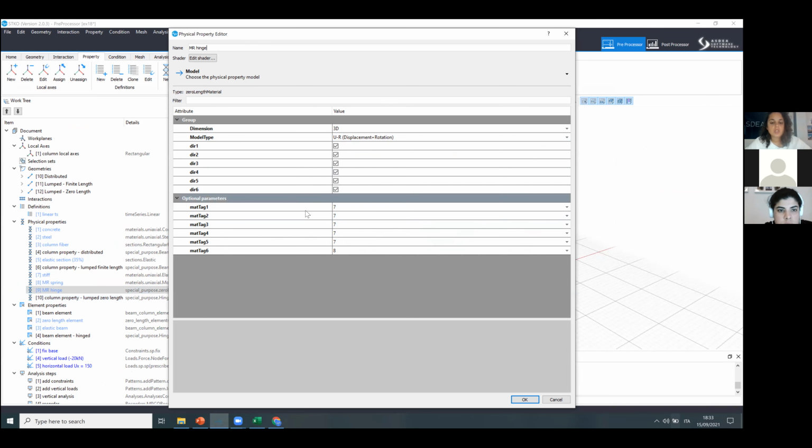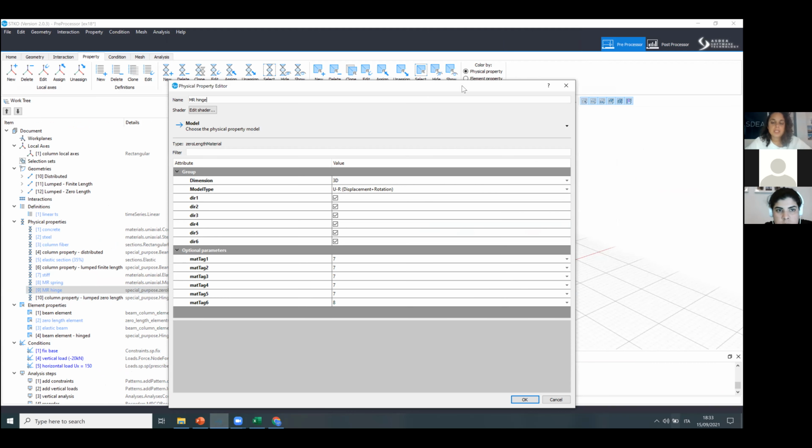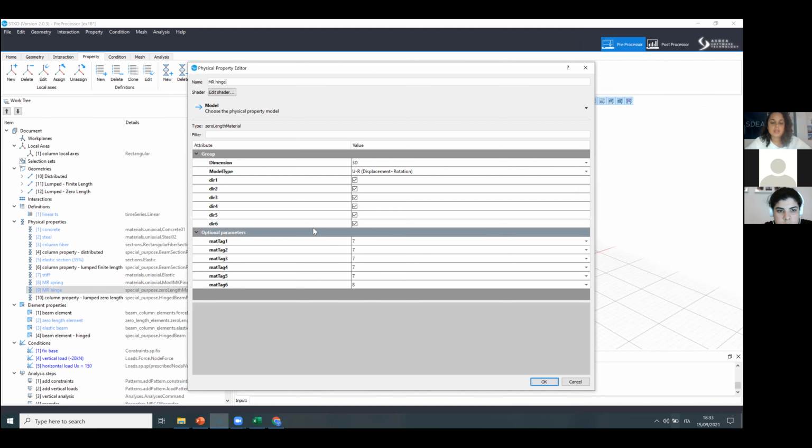So in each direction, in this case, we want to model plasticity just in the rotation around Z, because we are actually imposing an axial load, and so we want to see the deflection caused by that load, and that is our inelastic response. But of course, you can have an inelastic response in a different direction.